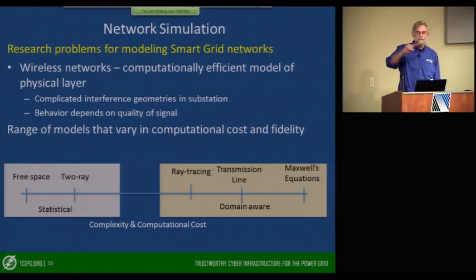Basically, you measure the distance, and then you take 1 over the distance squared, and that's how much the signal degrades, the same as gravity. Sometimes you get really fancy, and you degrade it by a power that's a little higher than 2 and stick another coefficient on there. There's something else that is not exactly free space. It allows for a second ray that's sort of reflecting off of the ground, and you combine those two.